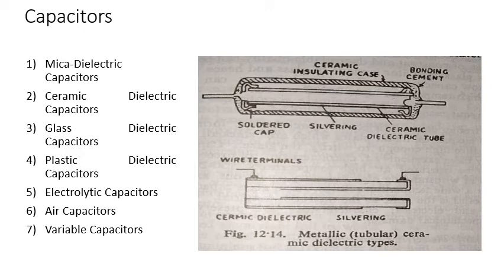Steatite has a permittivity of approximately 8, and other materials may give permittivities between 6 and 15. Their high frequency performance at frequencies above 50 kHz is very good. The power factor is reasonably low, and the temperature coefficient ranges between plus 80 to plus 120 ppm per degree Celsius. They operate at comparatively high voltages, that is 500 volts, over a temperature range from about 150 degrees Celsius down to extremely low temperatures.